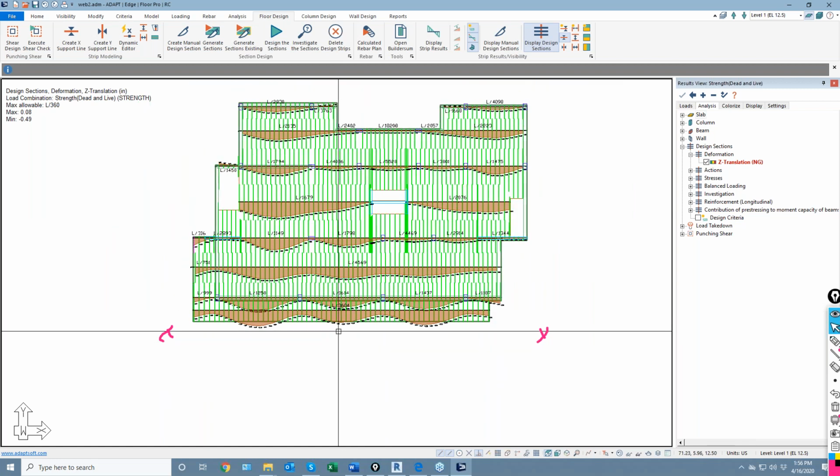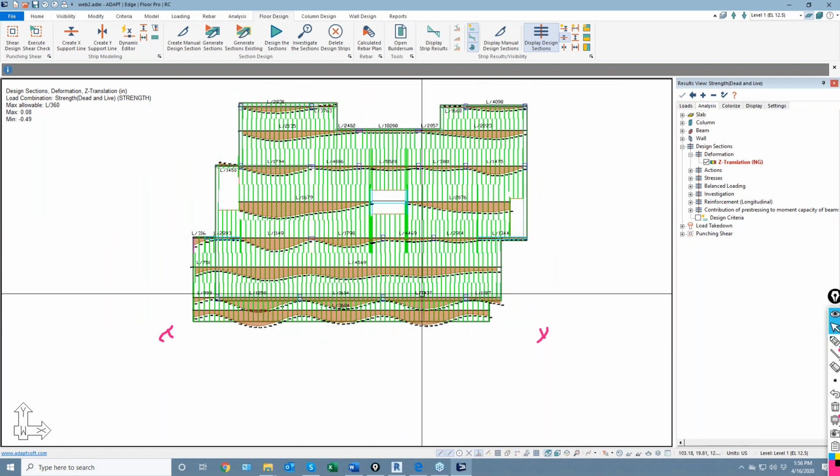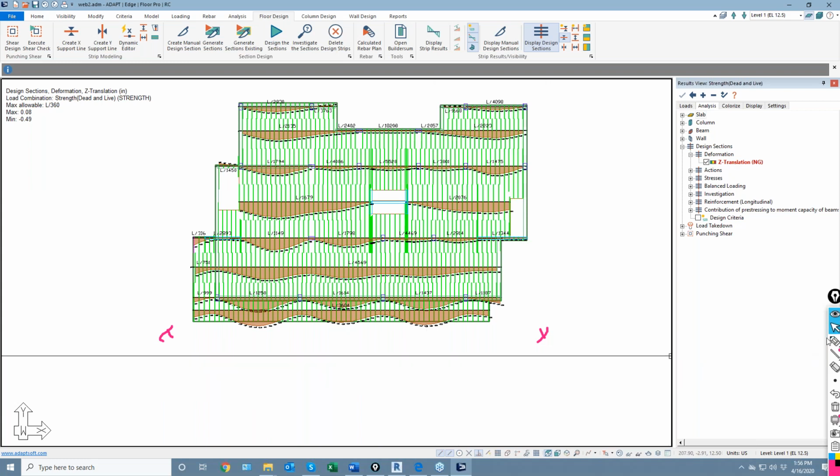So if you want more accuracy in these results, specifically for deformation on strips, I should have really cut it into spans and projected a point along here. This might be point 1, 2, 3, 4. Here you might put another point, 5, and then 6. And then we would have had 4 or 5 spans and had more reliable results if we're checking it in this fashion.